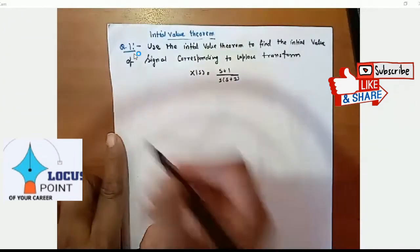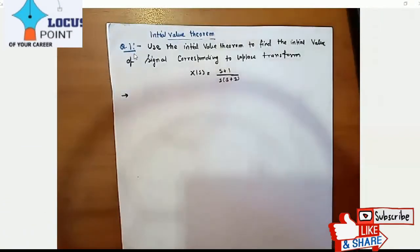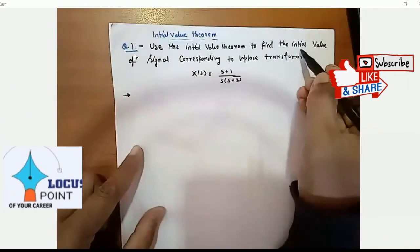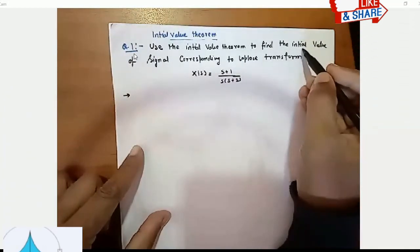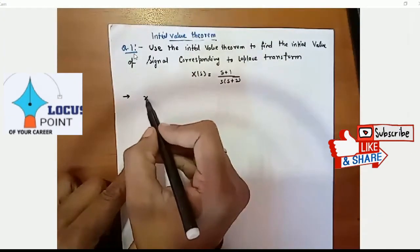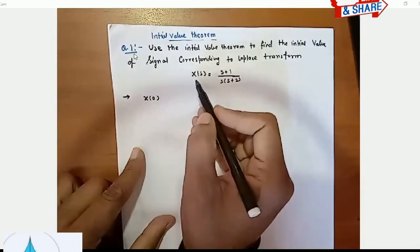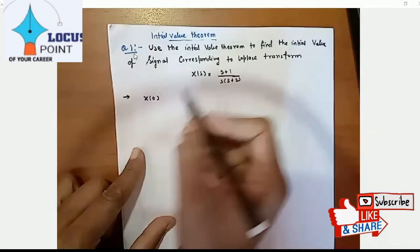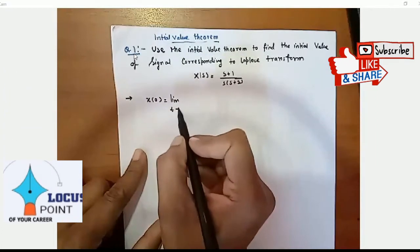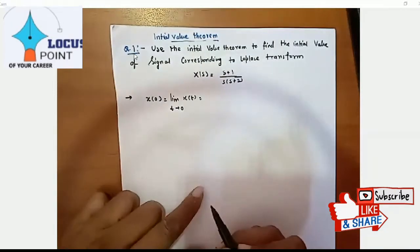Now this is the question. The question says to use the initial value theorem to find the initial value of the signal. Whenever they say initial value of the signal, they want x of 0, small x. This is capital X, the Laplace transform of this. Or you can say limit t tends to 0 of x of t, right?